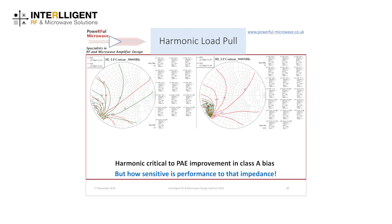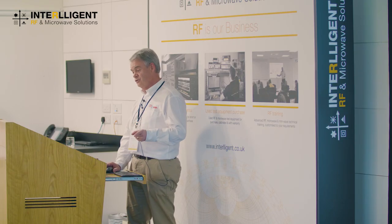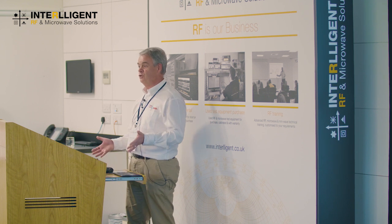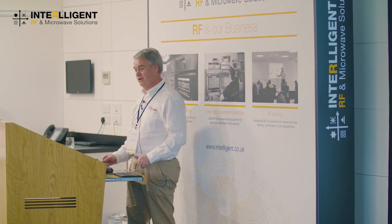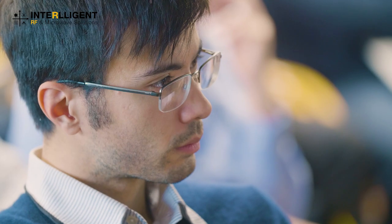Again, I've plotted now, this is an interesting one because this is the difference between the Class B, which is on the left, and the Class A on the right. You can see that with the Class B, the optimums are about the same place, but we're getting much more spread of effect around the impedance chart. Whereas in Class A, we're getting very little effect in efficiency until we get right to the optimums. And then we're getting an even bigger effect, but you have to be able to ride in that optimum. And that means if you don't hit the optimum, it's going to fall off very, very quickly. And that's because we're not producing very much harmonics with the Class A over most of the region. And then when you do, it can have a big effect, but you're going to be very, very sensitive to that harmonic level.